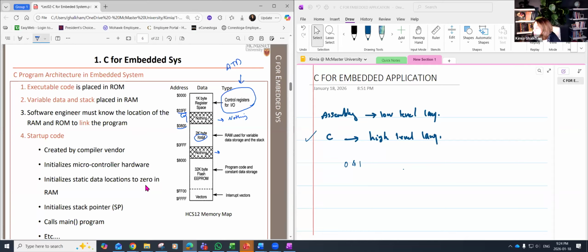And then you have the EEPROM for storing your code and your constants. Anything you put in there, you can just use as storage. And the last one is the interrupt vector, which is the memory location of the interrupt handler. This interrupt vector will prioritize interrupts and will save them in a queue if you have more than one interrupt at a time.